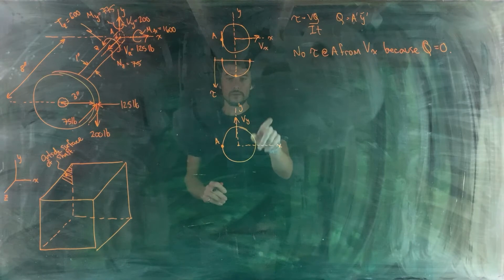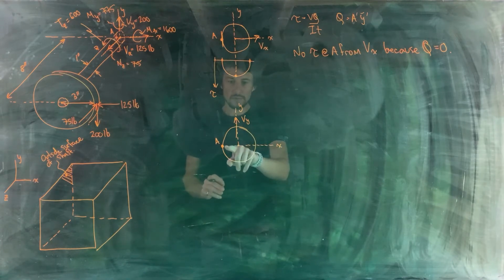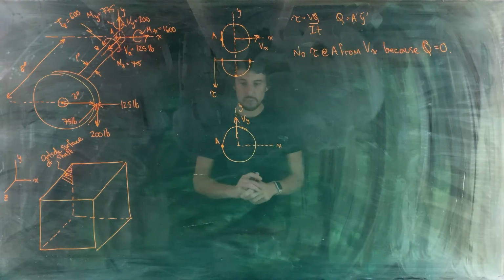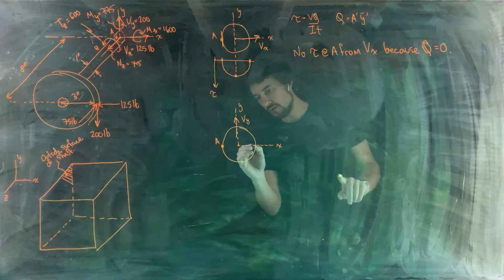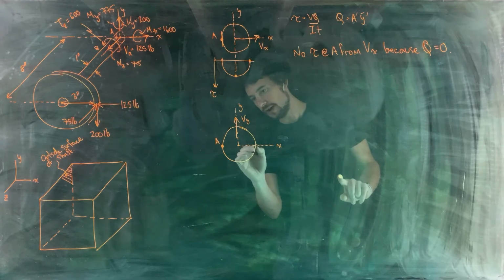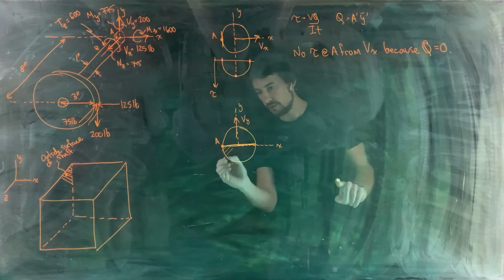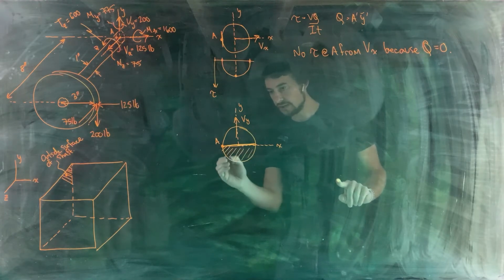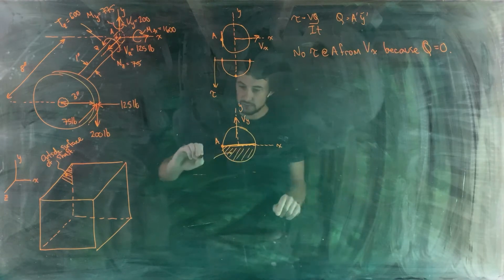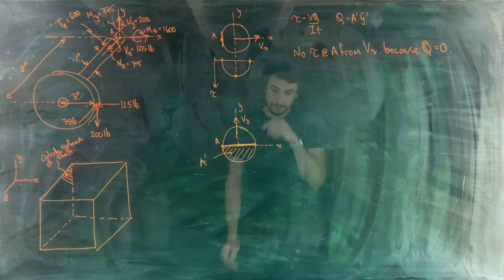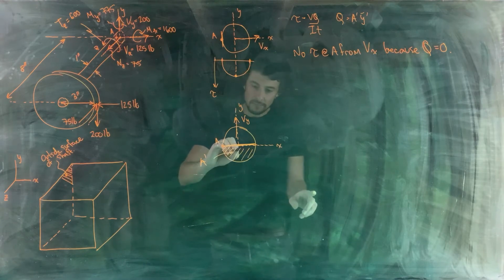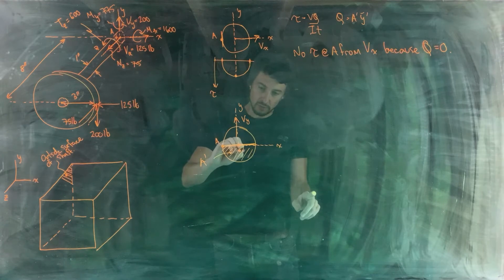For a shear force directed like that, if we wanted the shear stress at point A, we'd draw a line through the cross-section passing through point A, a line that is oriented perpendicular to our shear force. So this line, like that, and area A prime would be the area on one side or the other side of that line we've drawn. So there's area A prime, and then y bar prime is the distance between the centroid of A prime and the centroid of our whole cross-section.